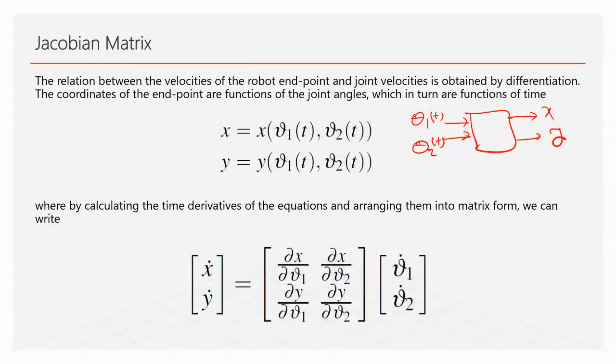The Jacobian matrix actually can be built up like this. So if you are looking for the derivative of x and y, each one a function of two other parameters, what you need to do is, your x derivative will be the derivative of x versus theta 1 plus the derivative of x versus theta 2, times the derivative of theta to time.